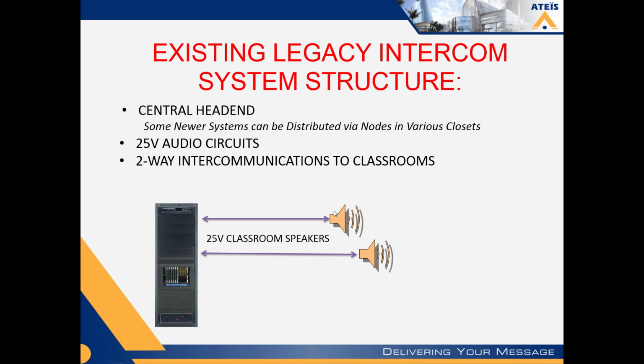Some newer systems, when I say newer, I'm going back probably as late as 8 or 10 or 15 years ago, these intercom manufacturers started coming out with what we call hybrid systems, which had nodes. So now instead of one big, huge rack at a head end, or maybe there still is a rack and a head end, but they also have nodes, so it's distributed equipment out through the facility and data closets, IDFs, MDFs, or electrical rooms.